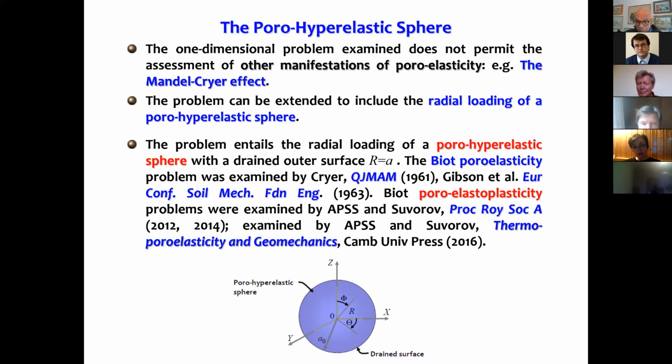The only problem is really that when plasticity develops in a material, you change its stiffness, and you also change its fluid transport characteristics. In other words, where material has yielded, you can get different fluid flow characteristics. So it's important to extend this work. Here we did the very elementary one where the material properties were elastoplastic, but the fluid transport properties remained the same.